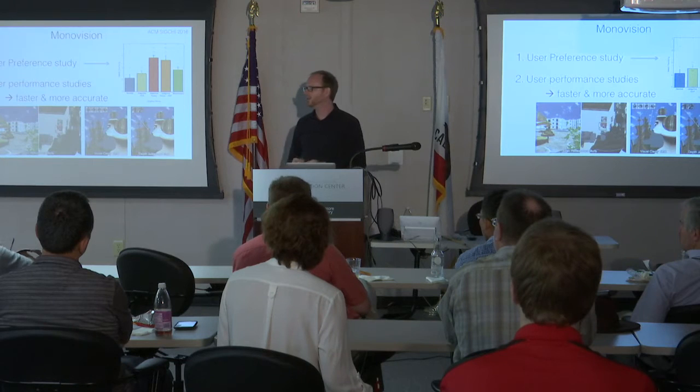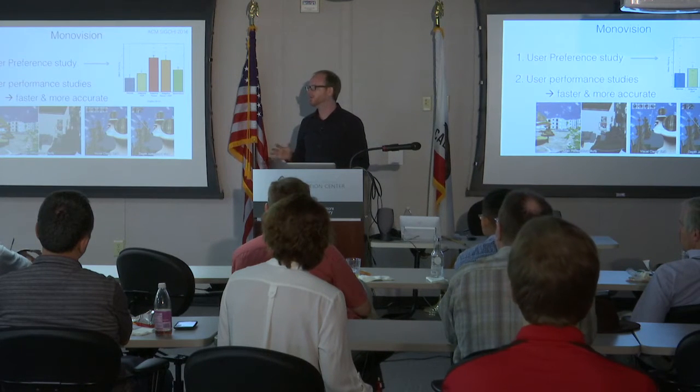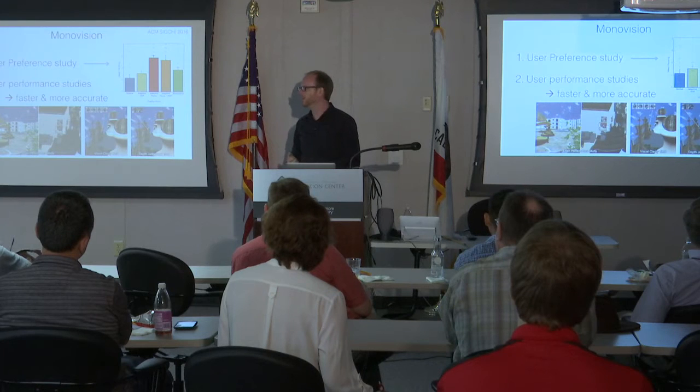So when you say adaptive focus, you're actually mechanically moving? So we're not mechanically moving anything. We have these liquid lenses, so we can program it into the lens. We can change the focal length, which is equivalent to using a static lens and actuating the screen. But for us, it's much easier because we can randomly switch between all these different modes. The user doesn't know what he's looking at, and we test them. Yeah, it's pretty much no latency. These lenses switch at about 15 milliseconds. The accommodation system takes about 100 to 300 milliseconds, so it's an order of magnitude faster.